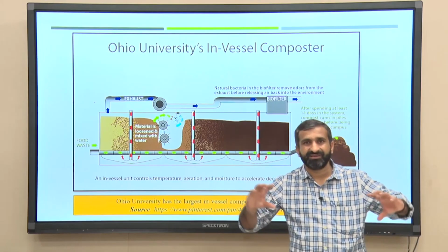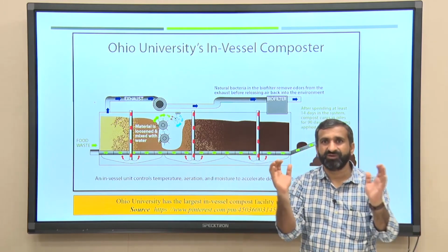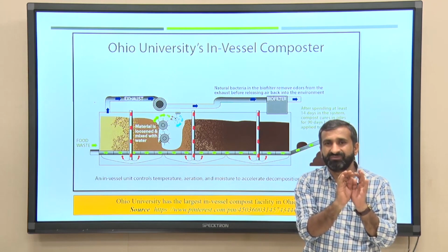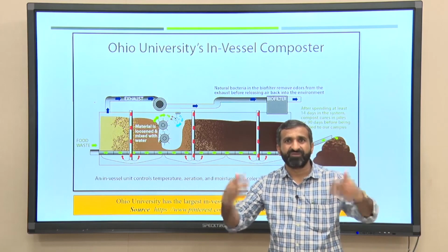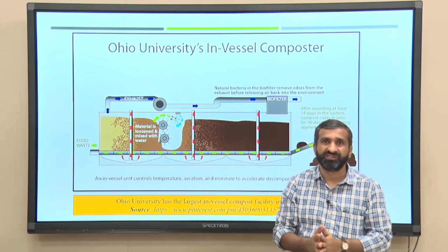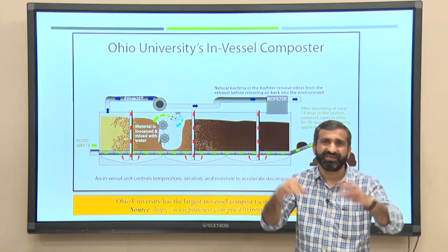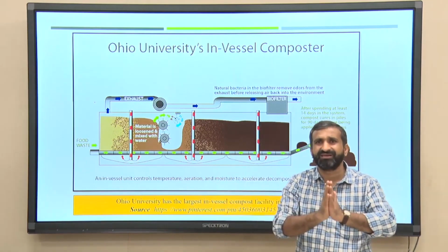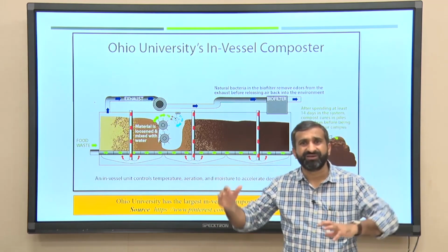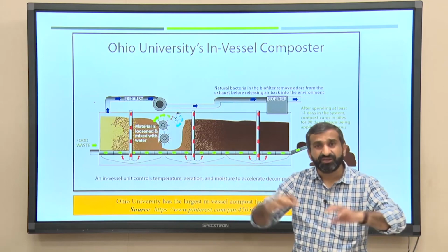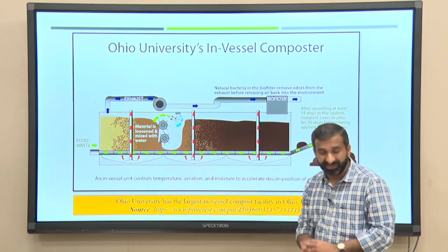What exactly is the mechanism? The entire material will be inside the vessel, and how best you will be able to feed the air, so that the thermophilic condition could be achieved, and in a limited period how best we will be able to degrade the material. I am not saying that within 3 days you need to get the product, but if you are getting matured material in at least 7 days, 8 days or within 10 days, that will be highly beneficial in such a reactor.